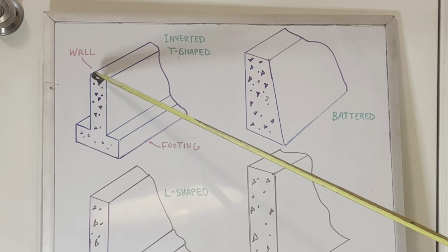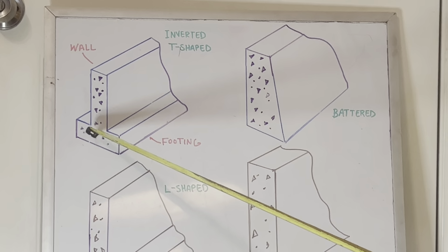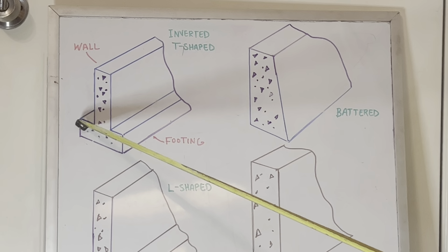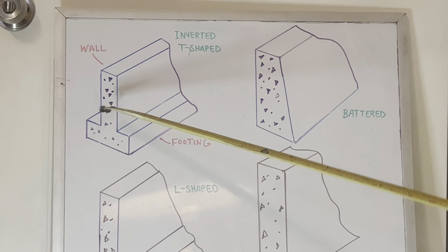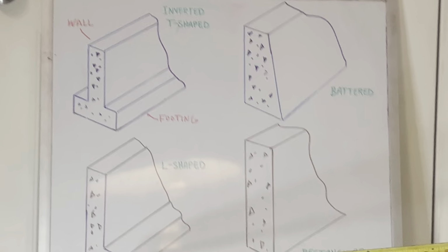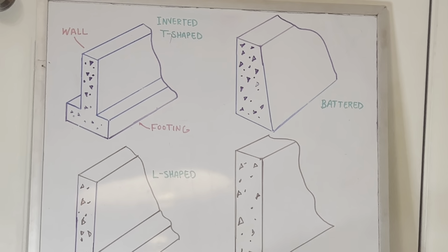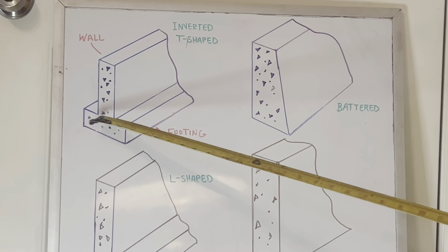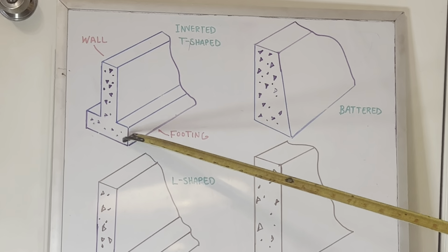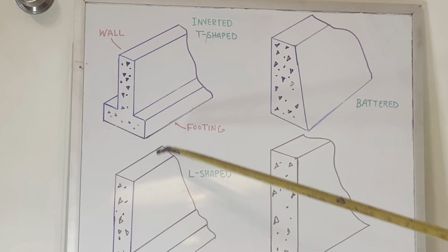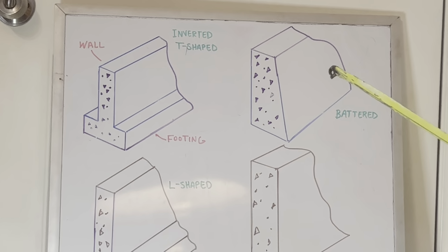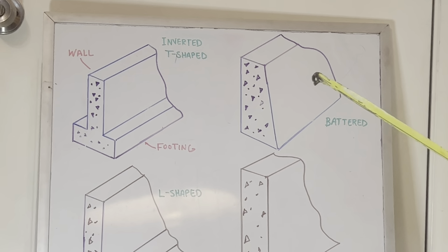If this vertical wall was just sitting on the ground, I just removed my surface area, so now I'm prone to sink into the ground or penetrate the ground. But with my footing, see how wide it is? It allows me to have more surface area. Let me keep on going.